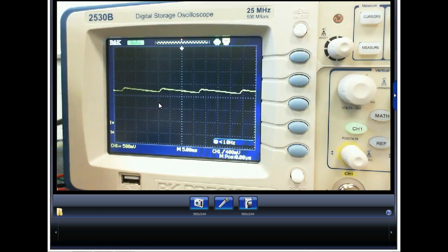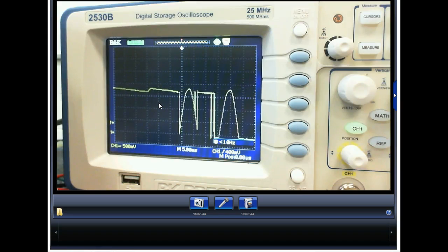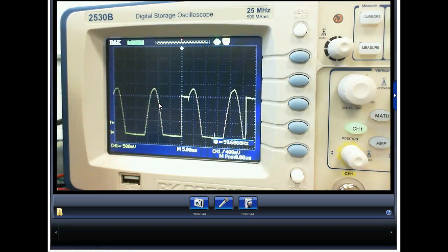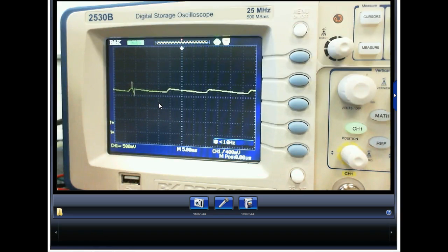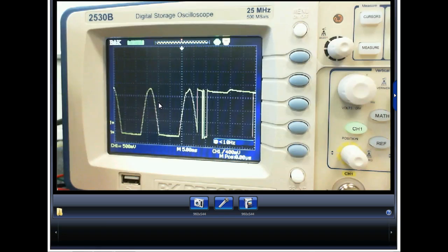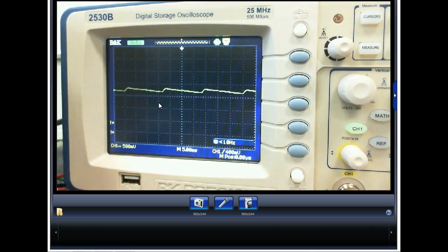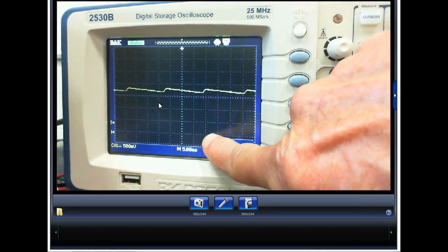Now, of course, it's snaking because we're out of our trigger range. That's pulsating DC. So it's going to 0 volts, 120 times a second. This is DC, but it's not regulated DC. Let me plug this in. That's DC. So it's not going to 0 anymore.